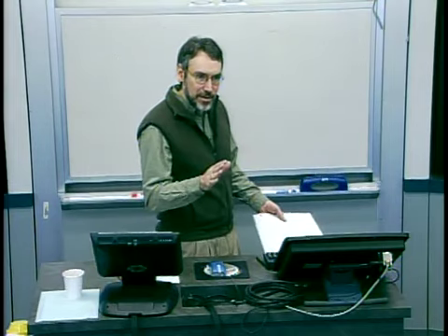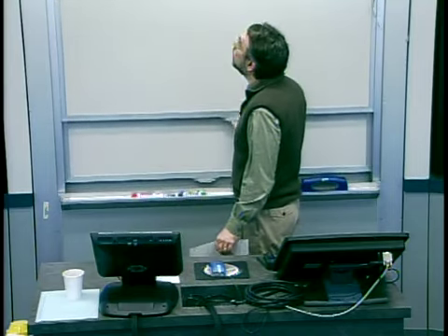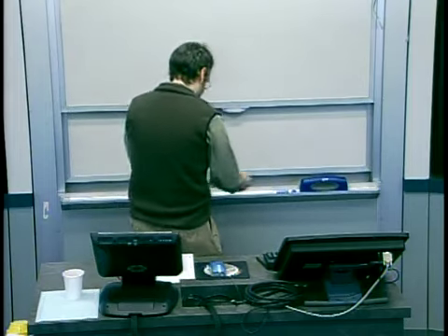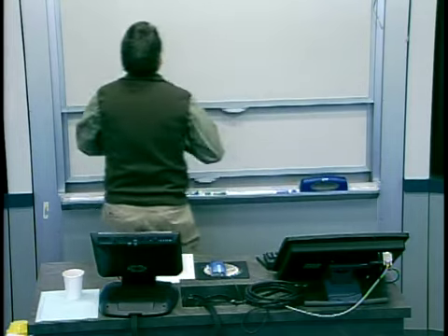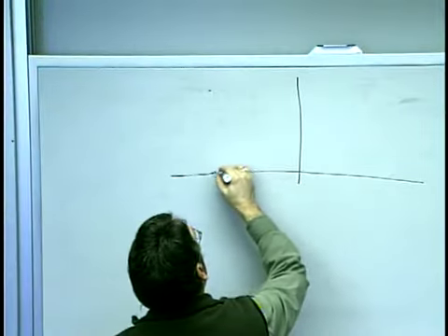So let me start again with the basic hypothesis test, because remember, all that a control chart is, is a running hypothesis test, where every new sample comes in, you're asking the test on the hypothesis: has the process shifted, or is it still my nominal distribution? So the basic situation with the hypothesis test, if you recall, what we have is our assumed distribution.